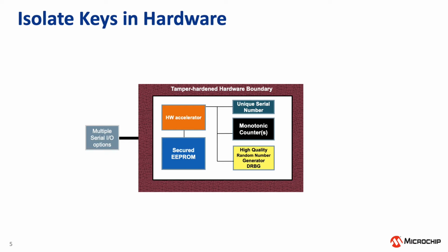The question is, why is the secure element a standalone device? That's a good question. Like I mentioned, the side channel attack protections are trying to protect against attacks that will try to alter the voltage, current, frequency, and temperature. So if you integrate this type of IP into a microcontroller, things become much more challenging and quite a bit more expensive, significantly more expensive.